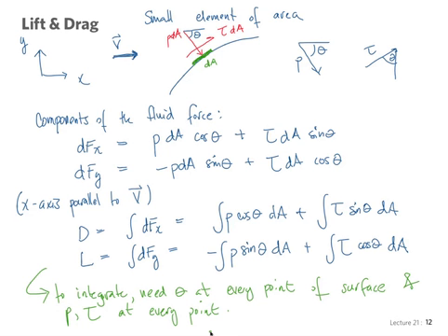most of the engineering work around this topic revolves around empirical results. And so we work with experiments, and we use what's called the coefficient of lift and coefficient of drag to calculate these forces from empirical observations, because this, as I said, is very difficult to know. So we use instead the coefficients of drag and coefficient of lift to calculate these forces, and those are obtained empirically.